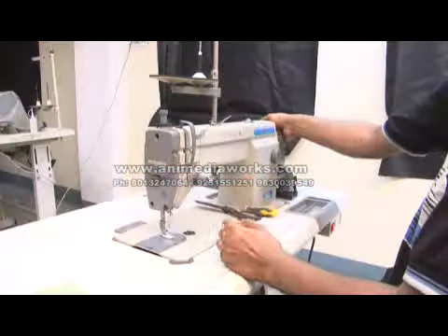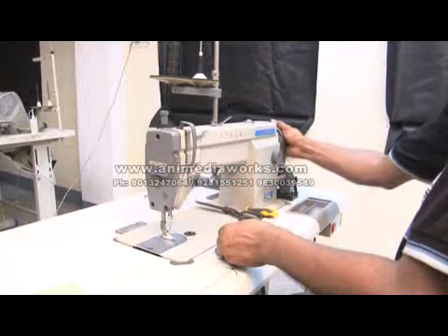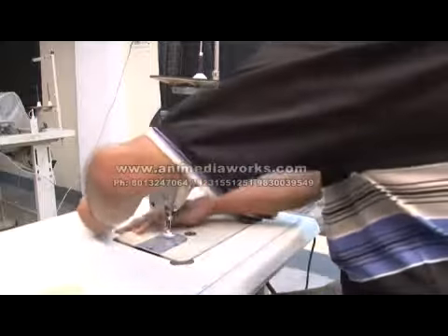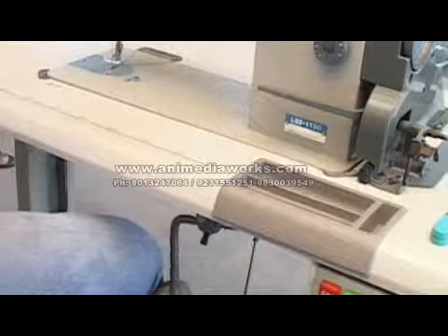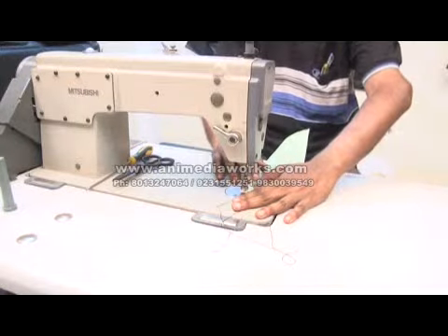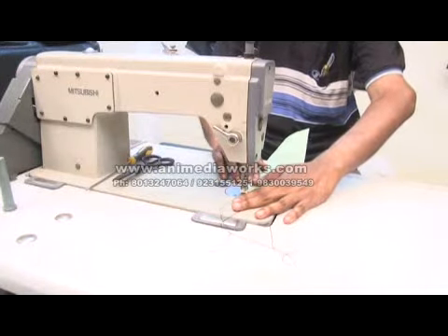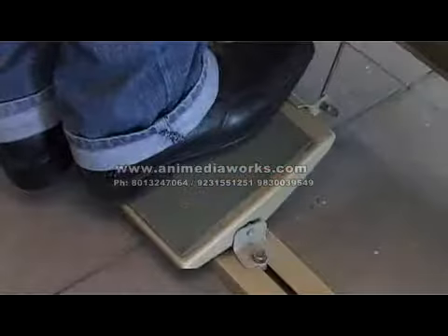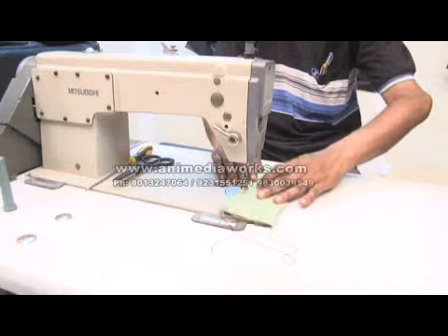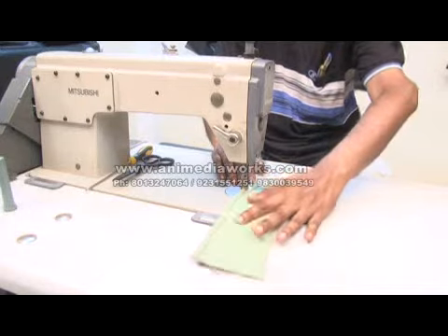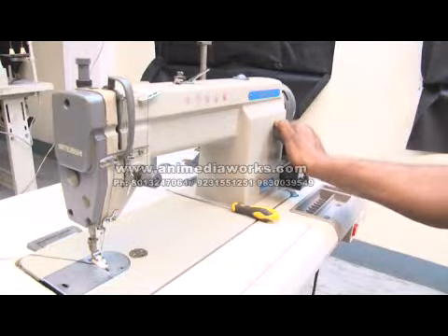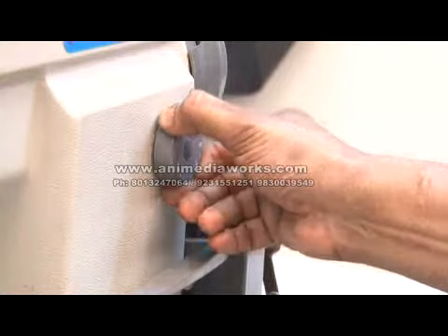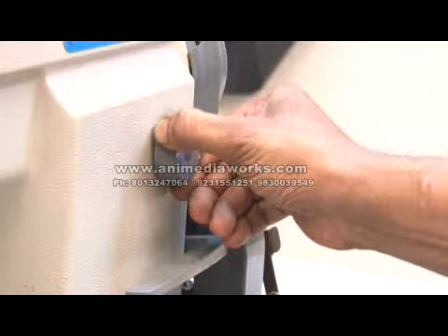Put on the machine, hold the threads, bring the needle to the highest point using the hand wheel. Raise the pressure foot using the knee lifter. Place the scrap leather between the throat plate and the pressure foot. Lower the pressure foot and use the foot pedal to stitch for a trial run. The stitch length can be adjusted using the stitch length regulator. The stitches are counted per inch, SPI.